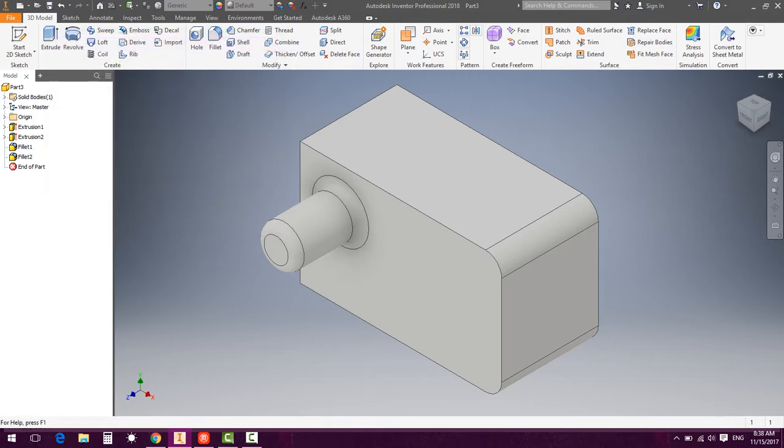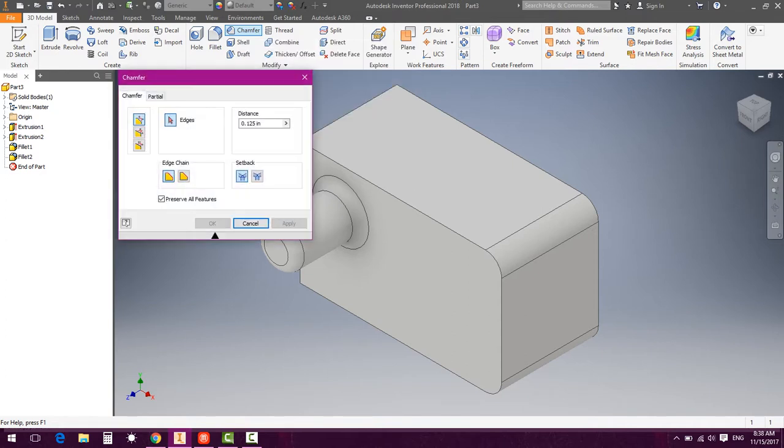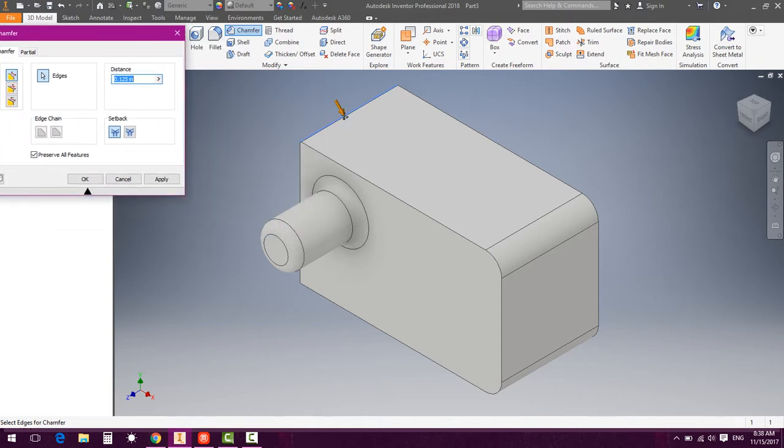The last thing I need to do is chamfer this corner. That's where we dock the corner off rather than rounding. This option is located right beside the fillet tool, so I'm going to hit that and pick that edge. Then again, I can change my numbers anywhere in here. I'm going to do that the same as I did the others. I'm going to go ahead and dock it at 2 inches.